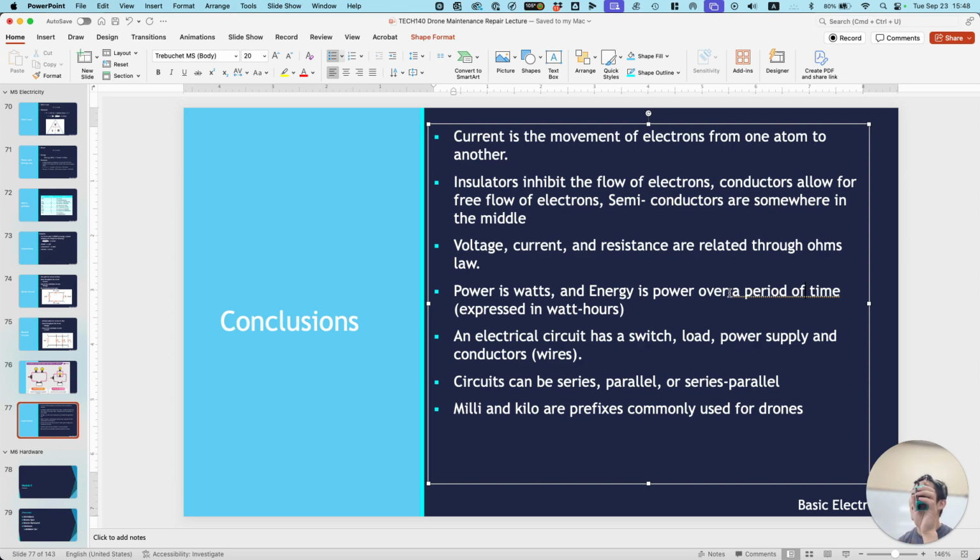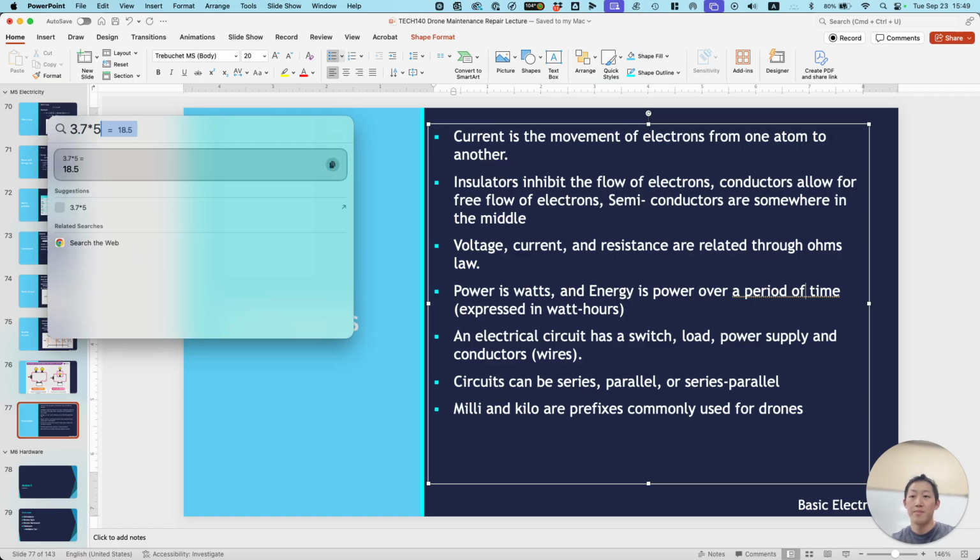That is like the rating of these. Do you have a 6S? What is the voltage on that? Does it say on there? 22.2. Okay. Actually, before he repeats it again, what would it be based off 3.7 volts per cell? We have 6 cells. What should it say on his battery pack? It's a 6S battery. 22.2? Is that what you got? Yeah. Okay. And then we also have a 3S battery. You have a 3S battery, right? Okay, so what would the 3S battery be?